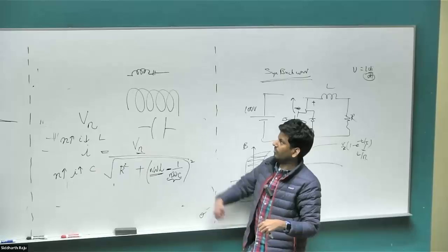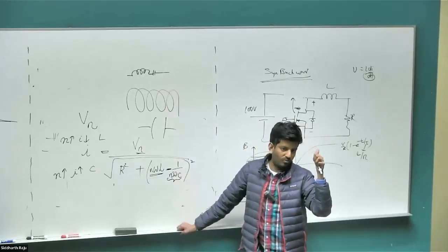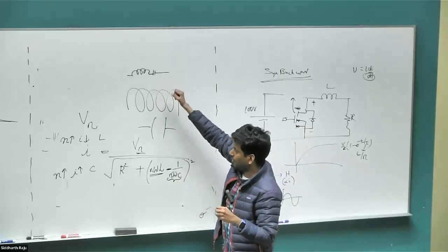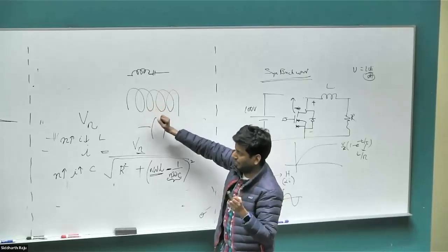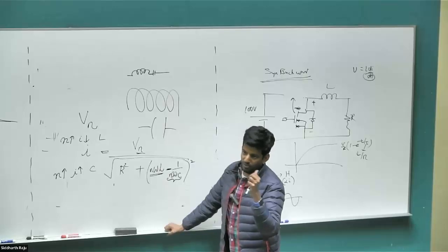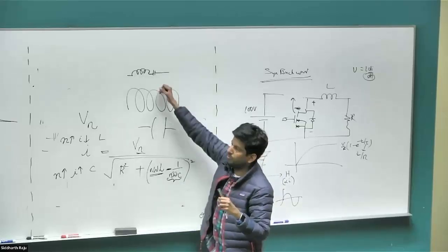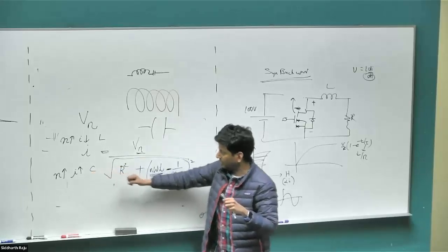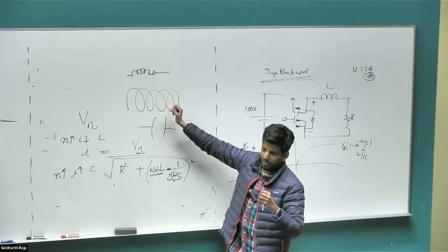So as your circuit becomes more and more capacitive, the current will start to increase as you go to higher and higher switching frequencies. So this parasitic component is a very big problem. Any inductor that you buy from, say, DigiKey, they would typically tell you it's rated for 400 kilohertz operation. You take that inductor and put it in a converter operating at 10 megahertz, it will not behave like an inductor, it will behave mostly like a capacitor at that point. So you would assume that the current ripple would reduce, but actually the current ripple would go crazy, because you're not putting in an inductor in that case, you're putting in a capacitor effectively.